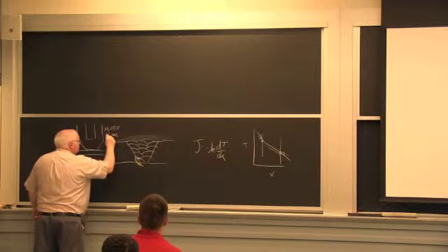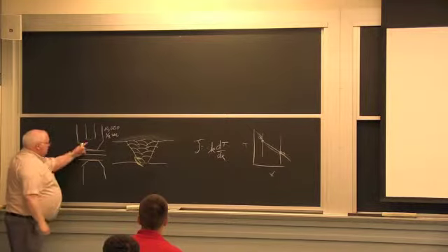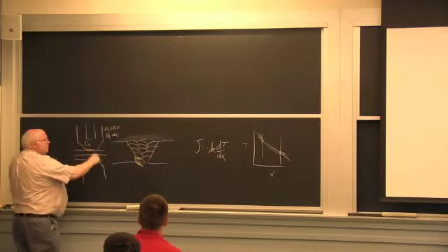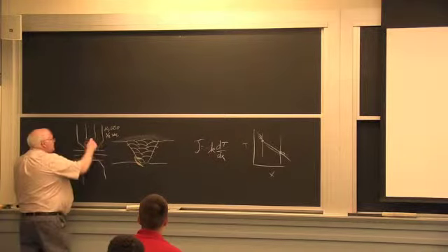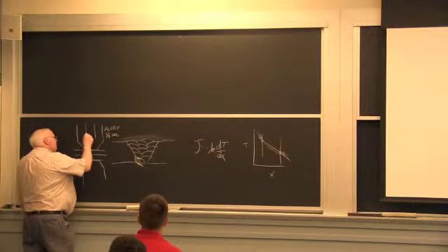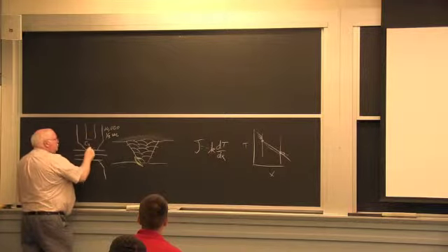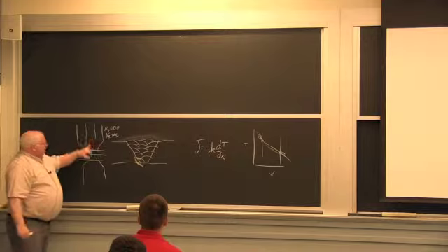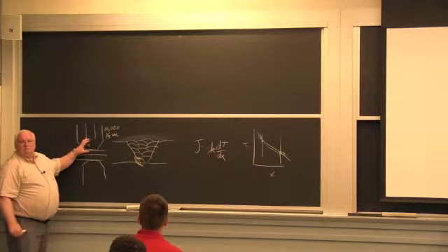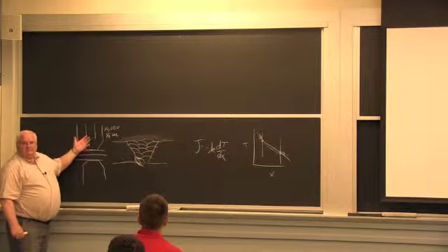I don't remember what the numbers are. You know this is copper, so you know the thermal diffusivity, right? And you've got 1/3 of a second. Will the cooling of the water here cool the tip before, during the time of the weld? Is the water cooling effective during the time of the weld or not?